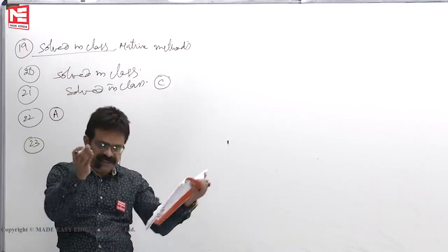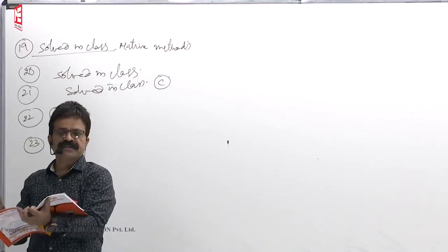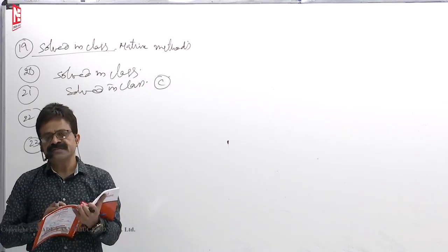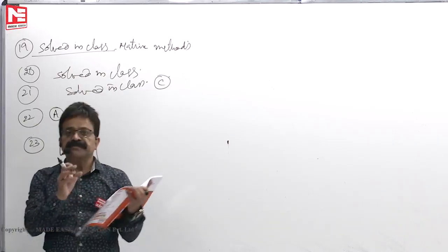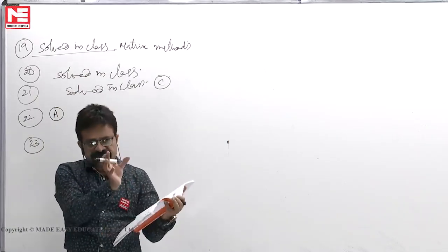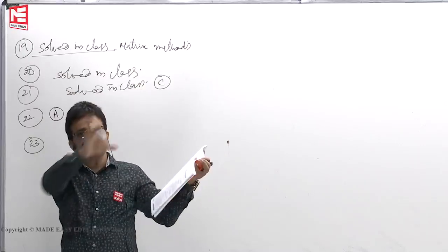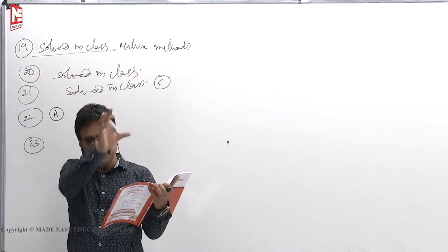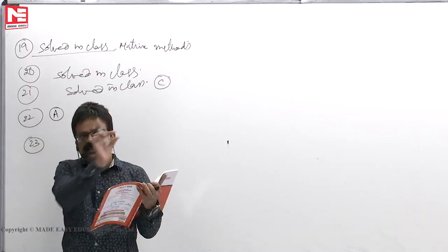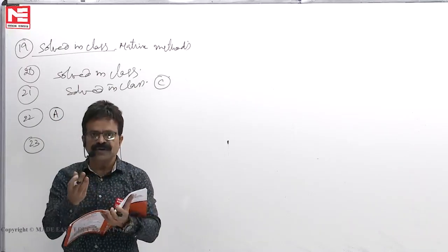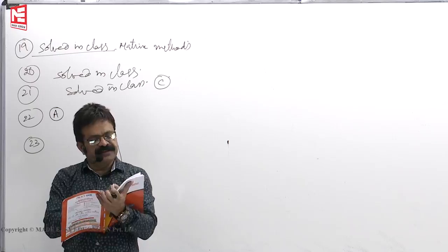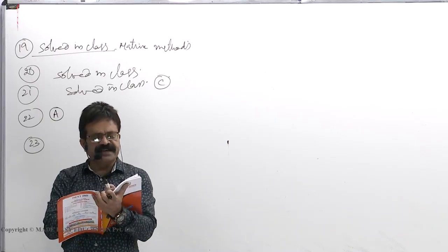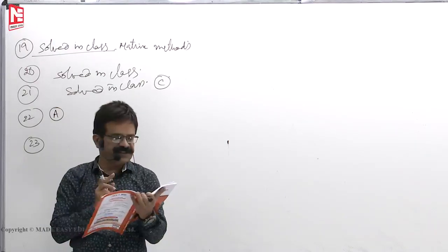Whatever redundants you take, the flexibility matrix is different and the compatibility conditions are different. Bandwidth means the positive elements, you get a band in a stiffness or flexibility matrix, and the bandwidth will generally be large. That means positive elements will be more in the force method. So assertion is correct, reason is correct, but reason is not the correct explanation.